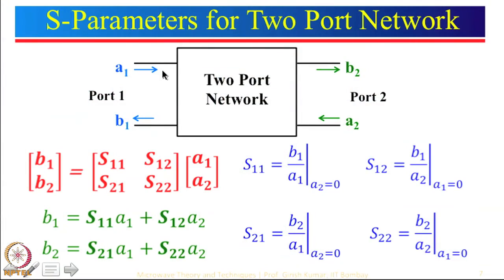So generally speaking, when we deal with S parameters, they are dealing with waves. So A1 is incoming wave, similarly A2 is incoming. So A parameters are incoming. So over here B1 is outgoing, sometimes they say, or leaving wave. So this is the outgoing wave or leaving wave. Sometimes in some books they also talk this as a transmitted wave also. Or over here they use the term reflected wave. So in this case, if this is incident, this is, you can say, reflected, and if this is incident, this can be transmitted wave. So it all depends how you look at it, but basically we just say that A1 or all A's are incident wave, all B's are reflected wave.